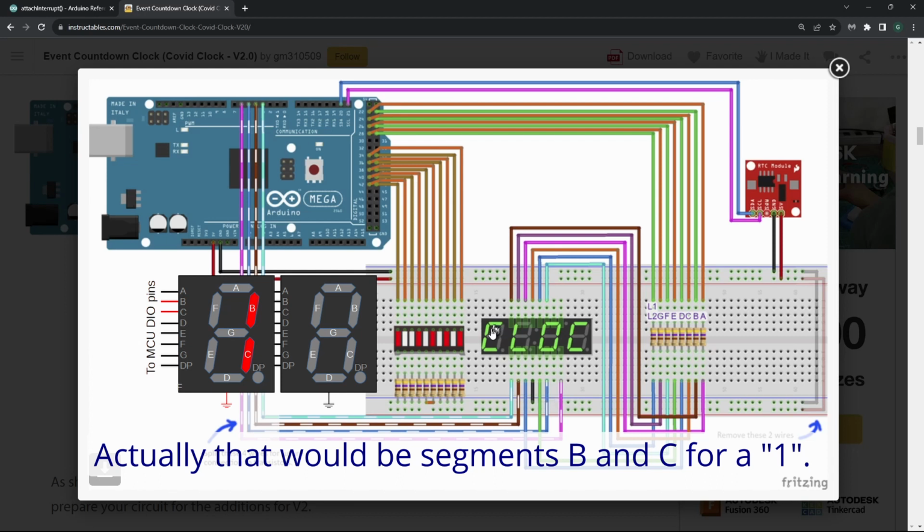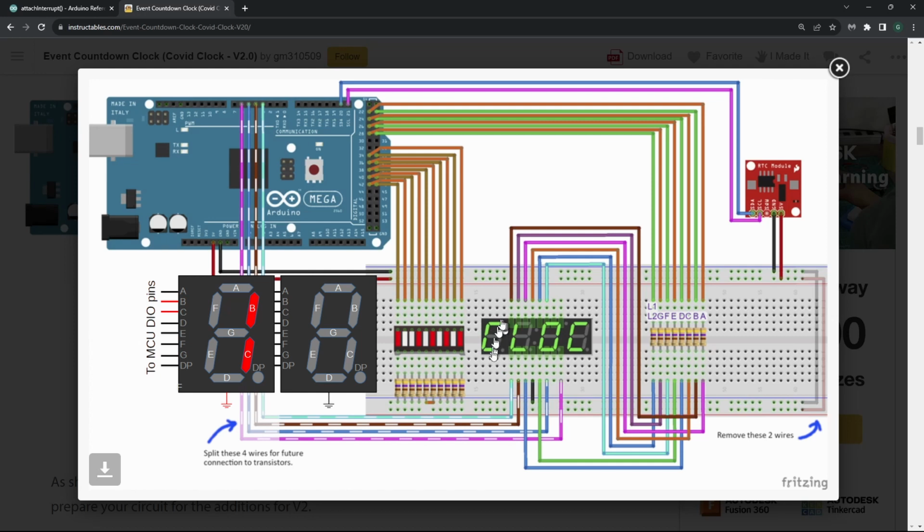So technically only a 1 is displayed here and the rest will be blank. Then if you want to display a 2, whatever the segments are, you would output a 2, make this one high, so this digit goes blank, and then pull this next one low, so now technically only this one is active. And if you do that quickly enough, it looks like the display is steady.